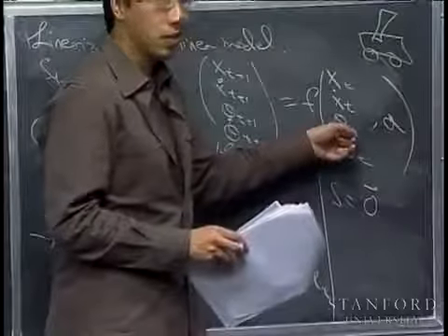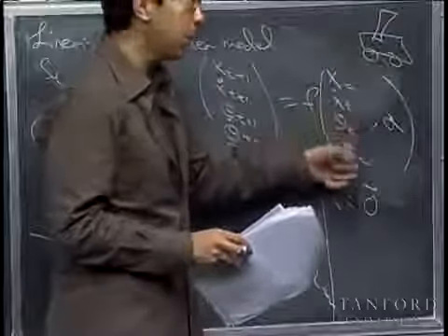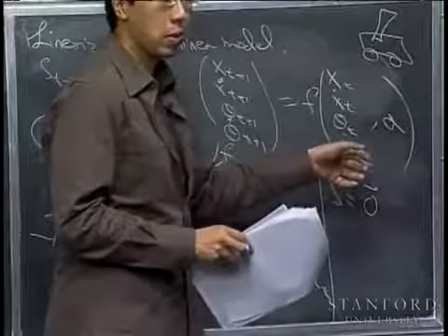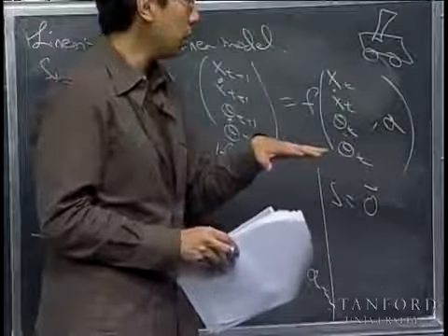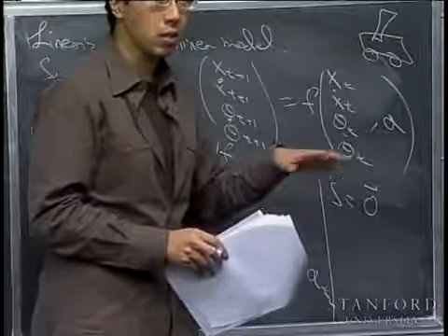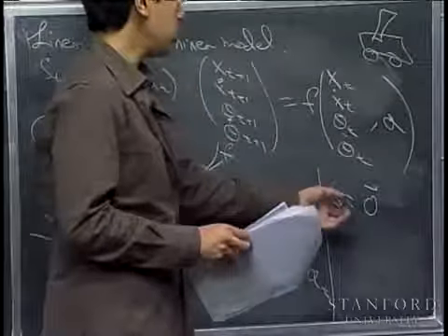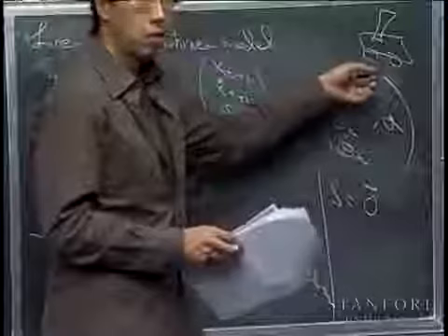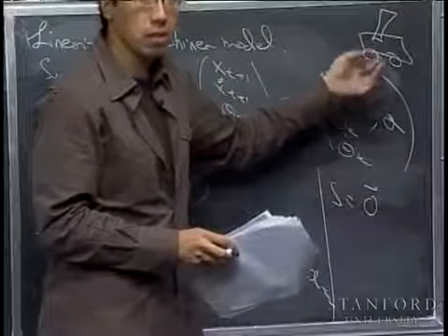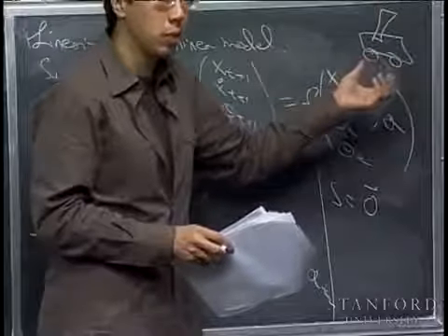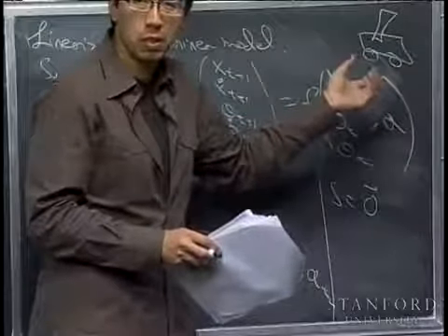It depends on whether upright is 0 degrees or 90 degrees, I guess. But so you choose whatever state corresponds to having the pole upright at zero velocity and the cart near zero velocity and in the middle of the track. So you would usually choose that as a state to linearize your inverted pendulum dynamics around, since that's the region where you might want your approximation to be good.